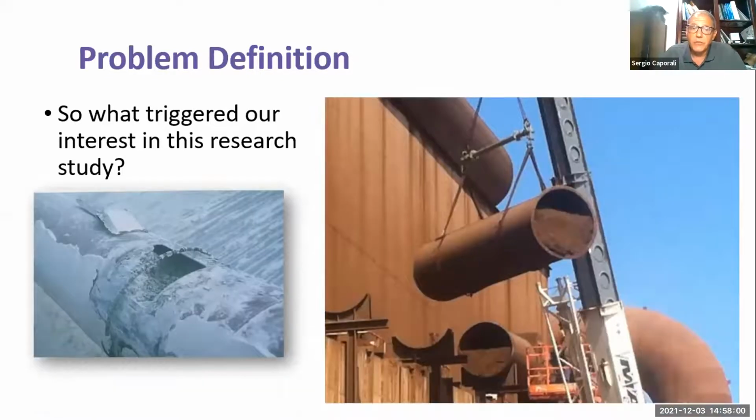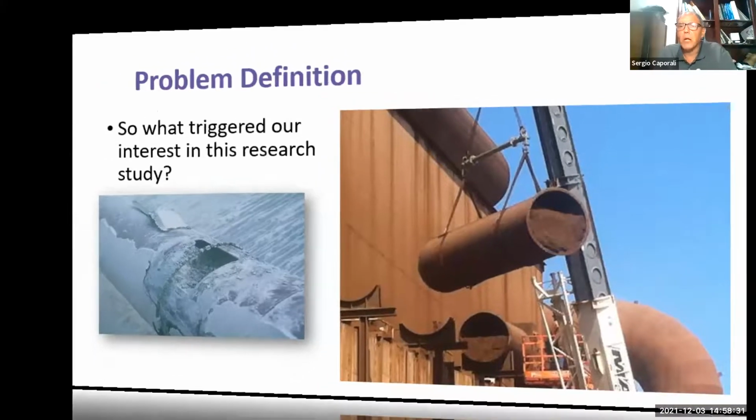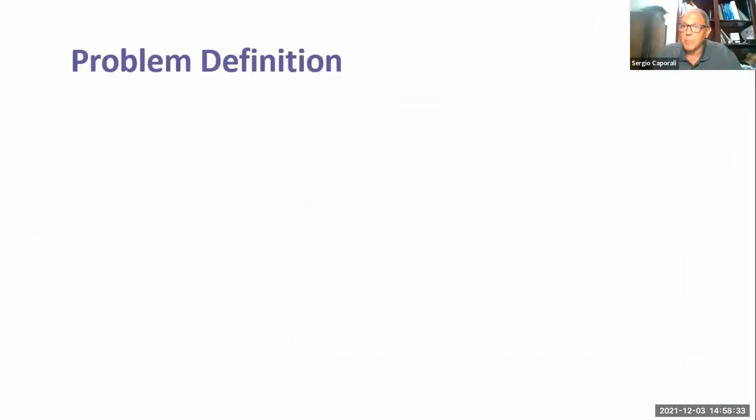When you look at the pictures presented in this slide, you see on the left-hand side a duct that is almost completely filled with material. This is an industrial ventilation duct. It should not be filled with material. It should be perfectly clean. On the right-hand side, you see a duct almost 3/4 filled with metal powder. It was disassembled because part of the duct started to fall on top of the workers. So we have this problem, even though systems are being designed with the traditional method.